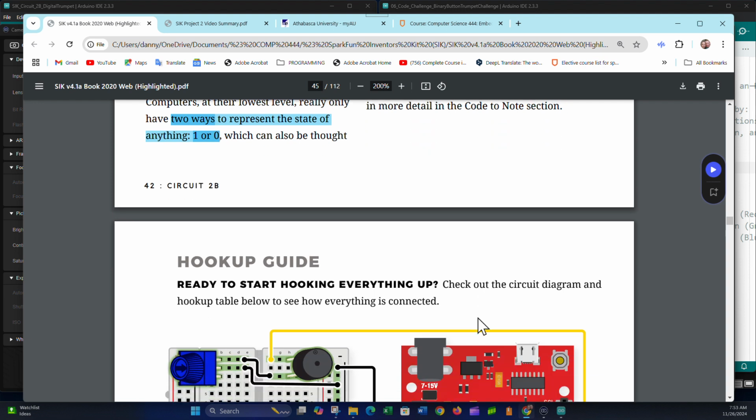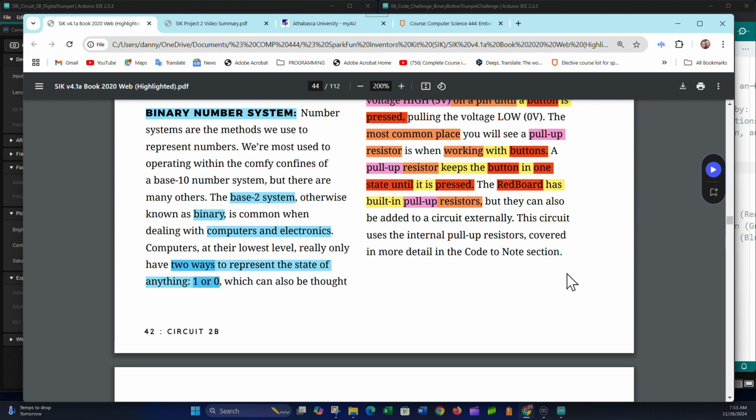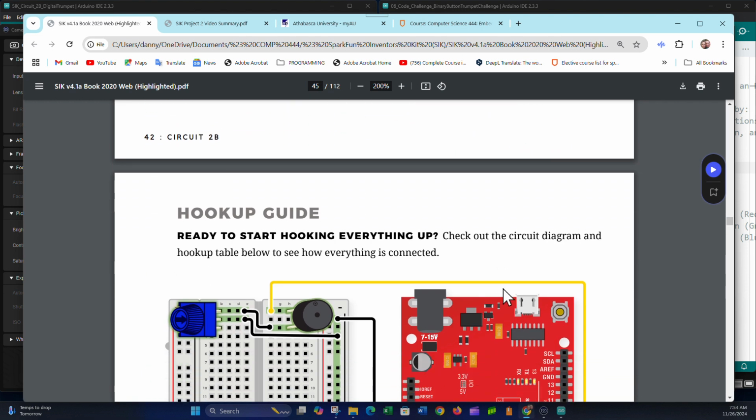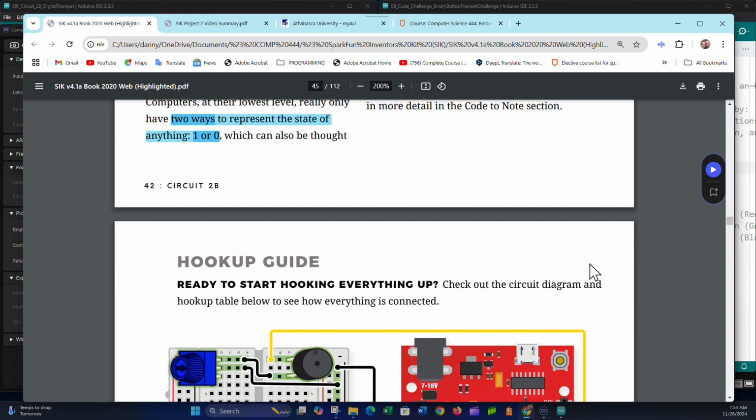Normally you'd call the pinMode function passing in 2 arguments, the first being the pin that you're setting up as an input or output, and the second typically being INPUT or OUTPUT, indicating if this pin is for output or input. But in the case of input, instead of the keyword INPUT, all uppercase, you put the keyword INPUT_PULLUP, still all uppercase, and that creates the pin as an input but activates the internal pull-up resistor. Alternatively, you could create a pull-up resistor in hardware, by physically putting a resistor between one of the button terminals and the 5 volt power rail.